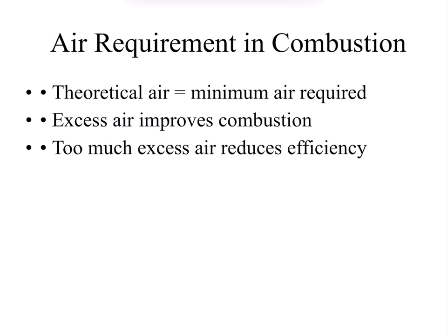What is the air requirement in combustion? Theoretical air represents the minimum air needed for complete combustion. Engineers usually supply excess air to guarantee complete burning, but excessive air can reduce efficiency. So theoretical air is equal to the minimum air required.